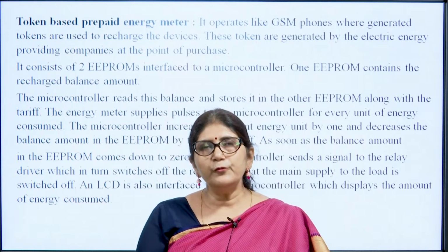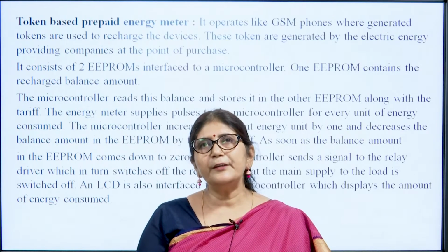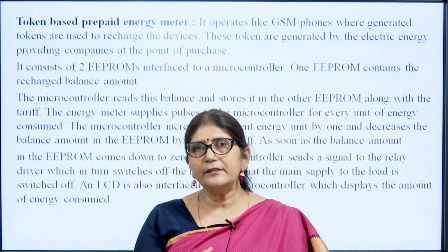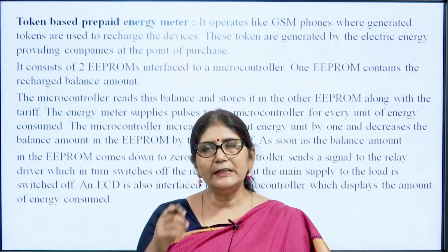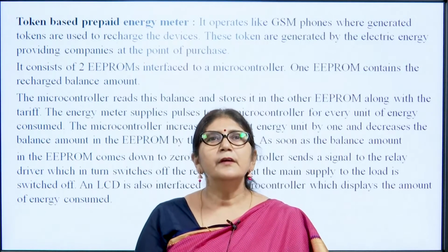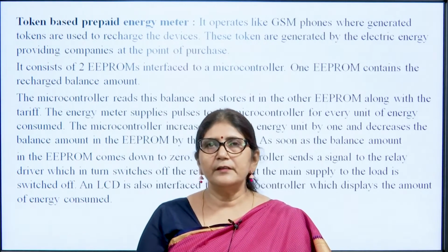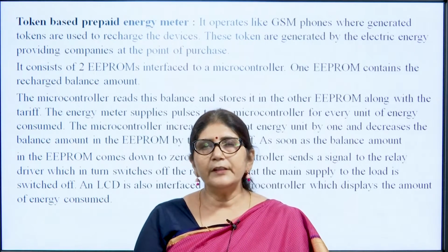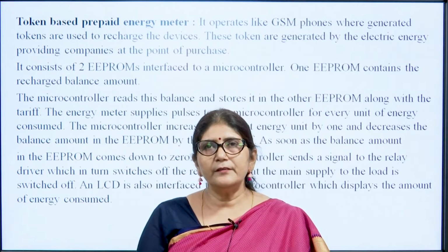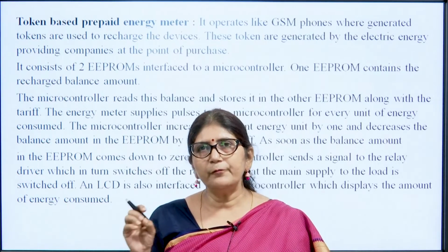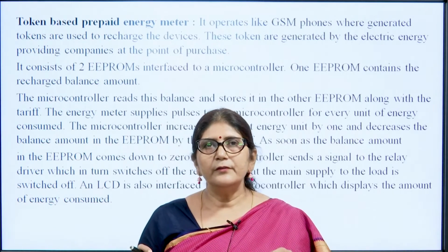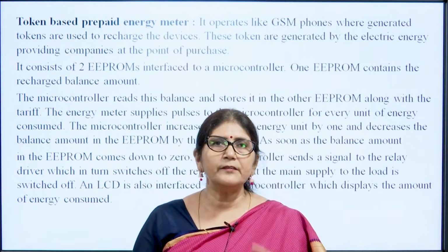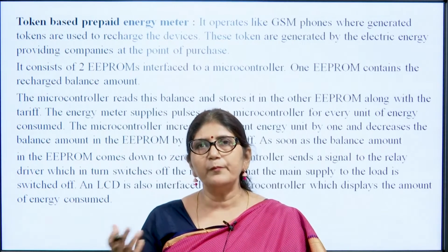So, it consists of two EEPROMs interfaced with the microcontroller. One EEPROM contains the recharge balance amount. EEPROM means electrically erasable programmable ROM, and the microcontroller reads the balance and stores it in another EEPROM along with the tariff. So, an energy pulse goes to the microcontroller for every unit consumed, so that the microcontroller increases the energy unit by 1 and decreases the balance amount in the EEPROM by 1.